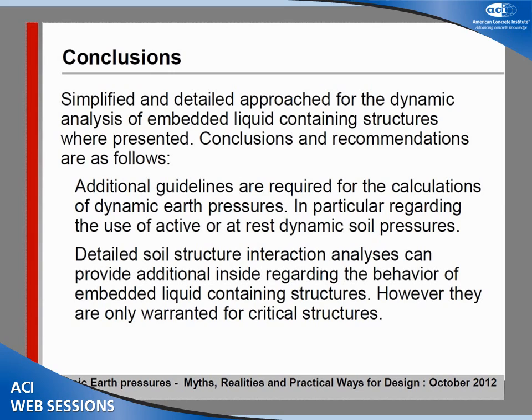Because this was under seismic conditions, at least for a nuclear structure, all the load factors are just 1 because it's the maximum safe shutdown earthquake. So all the load factors were 1, and the safety factor against sliding was less than 1. That meant that the structure is sliding, and then we considered the KA conditions.